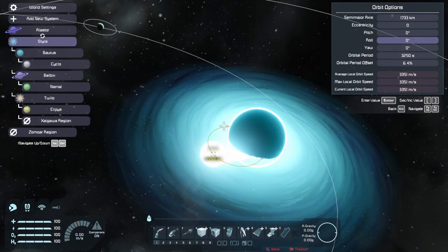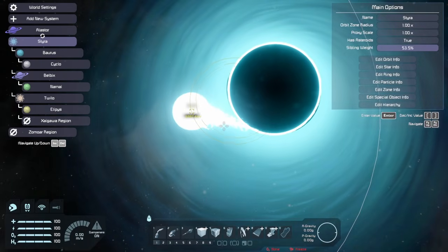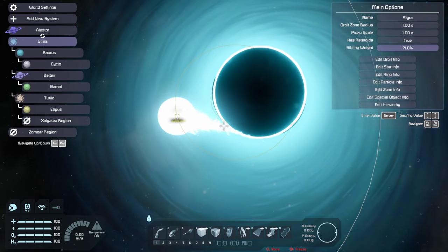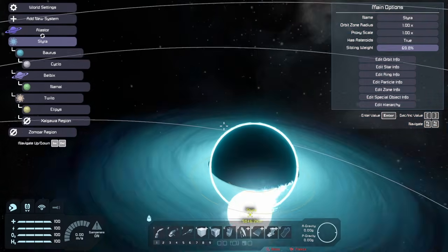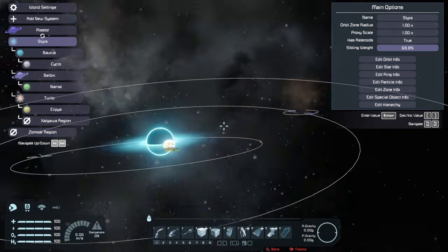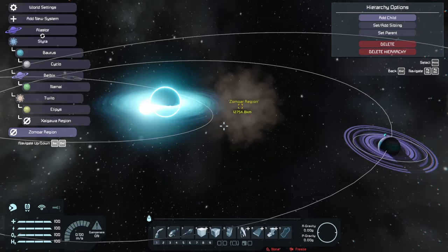Let's take one more look at the siblings. Sibling weight controls the apparent mass balance between a pair of siblings. Setting one higher or lower will shift the center of gravity between the bodies and make one look heavier. However, the total distance between them will remain constant. This one looks odd floating out here, so we'll give it a parent.